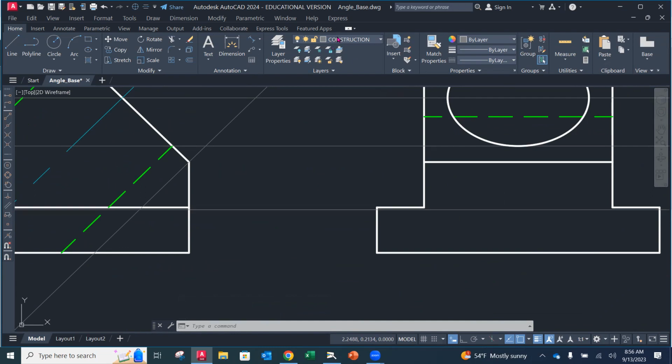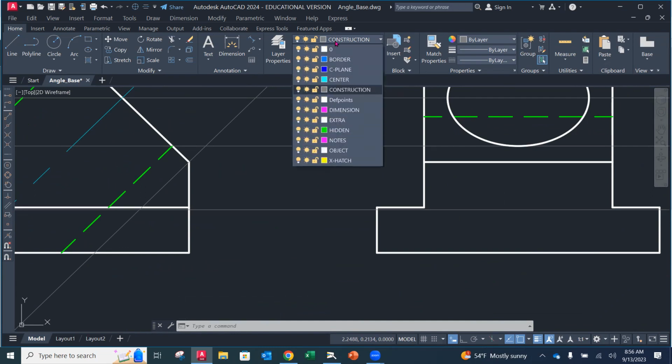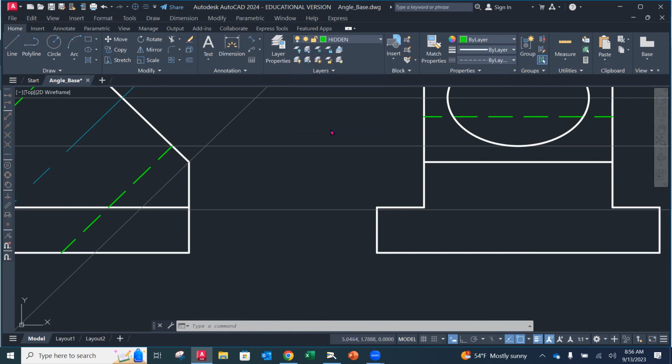So now this one is gonna be a hidden ellipse because we're looking through material and it's gonna be kind of a leftover at the end. So now we're gonna go to hidden, go back to ellipse. We're gonna find the midpoint down here because this is where the center is. This is where that center crosses. Midpoint, go straight up. And then now our radius is gonna be 0.75.